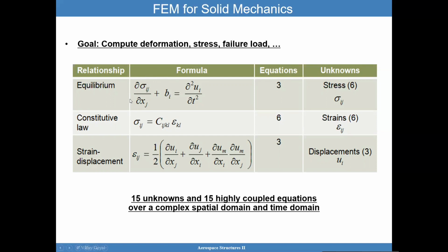This is basically the summation of forces equals ma. Think about it. So this acceleration right here, u is the deflection, and these are body forces. And so for stresses, you're taking the derivative of stresses with respect to the position, plus the body forces equals the accelerations. And these are the deflections.